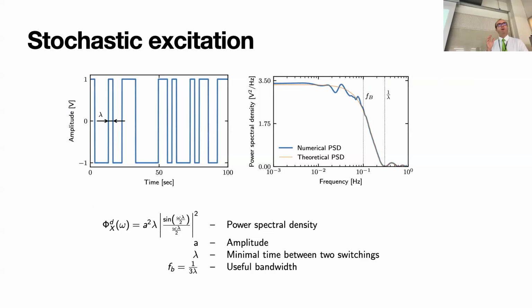This has actually two benefits. First, when we do an excitation with sine waves, we need sine waves to be crisp. There should not be any nonlinearities in the sine waves, because if there are, they will mirror on the output. And that requires quite complex hardware components.